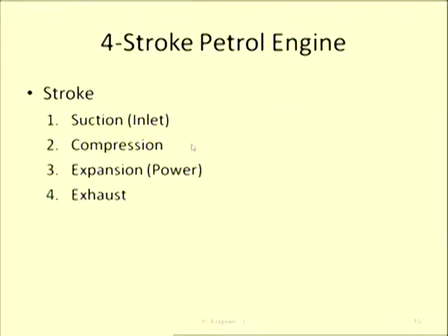Once your fuel has gotten into your engine, the compression process will start. So the piston will move from bottom dead center to top dead center. So your confined volume will be compressed. So the volume is fixed and your charge, that is either air fuel mixture or only air, will be compressed. So that is called compression stroke.